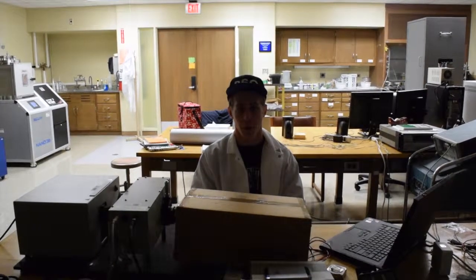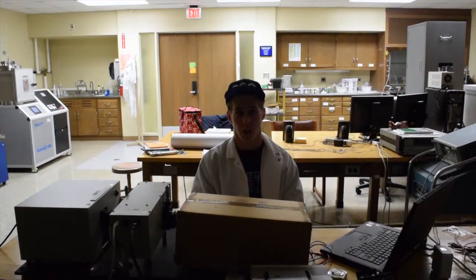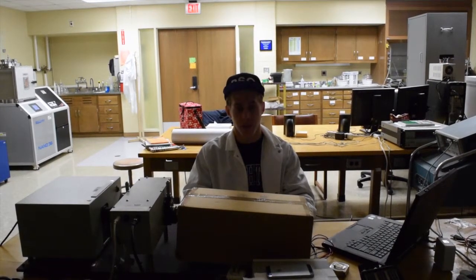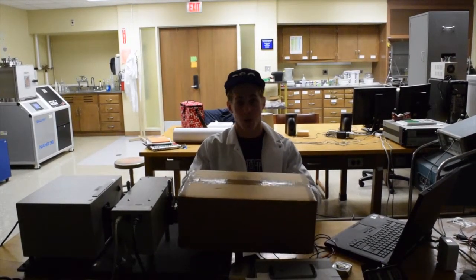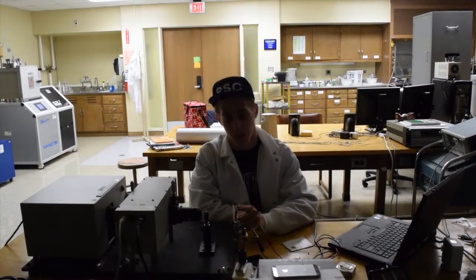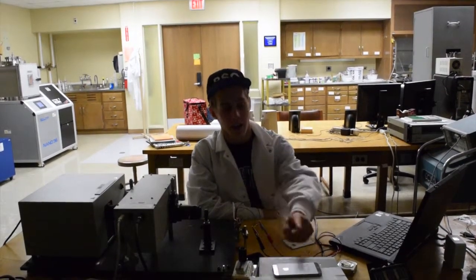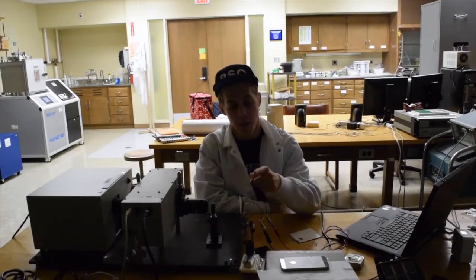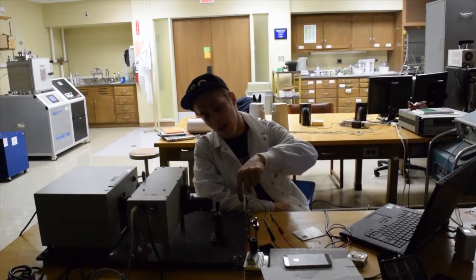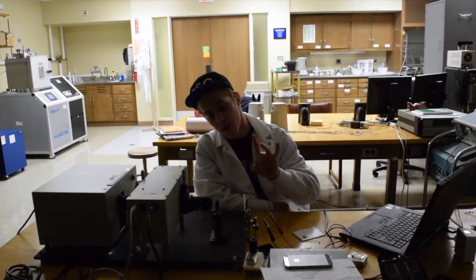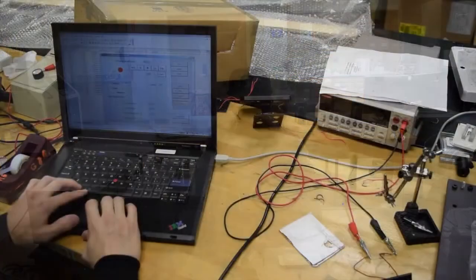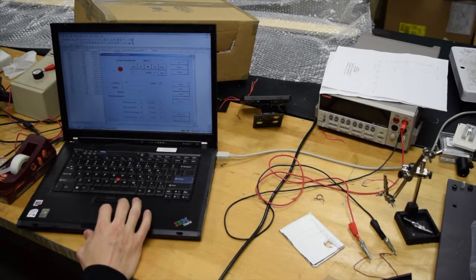Okay, so to review what we've done in order to find the charge carriers leaving the cell, we've built a shade to get rid of some of the ambient lighting in the room, which we'll remove here. We've wired an encapsulated silicon solar cell into our Keithley power meters and mounted it 5 inches away from our light source and covered all the cell except for a surface area the same size as the power meter we'll use to find our power density. And we'll move into our Cornerstone utility program.